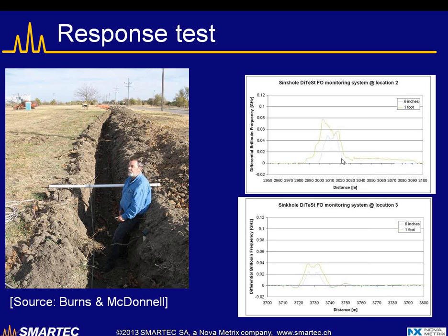You can also notice that when the movement is increased, we don't really see a large increase in the strain, but rather the strain is distributed over a longer and longer area. So this means that basically we are pulling the cable out of the ground over a longer and longer area, so it's possible to continue monitoring without breaking the cable, even if very large strains are applied.